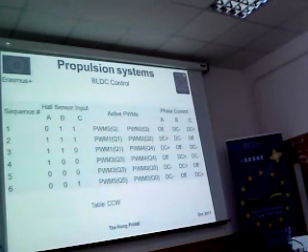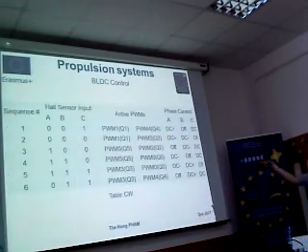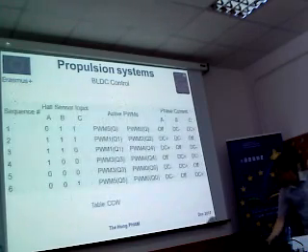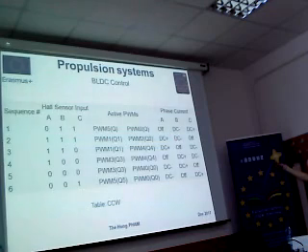You can see in this one, from A to C, right? Okay, so now in this situation, we mean from C to B, right? And then from A to B. So the order of supplying power to the two coils at one time will be changed in order to change the direction of the motor. Okay.